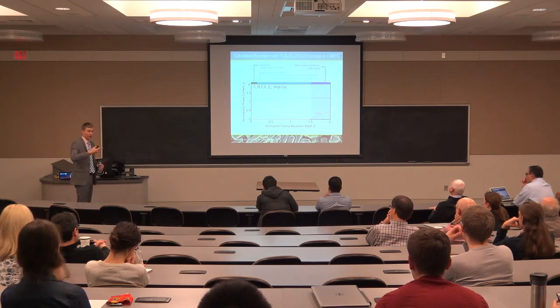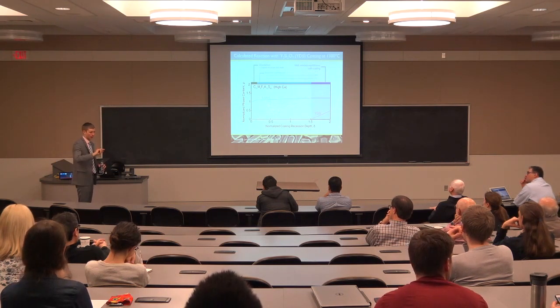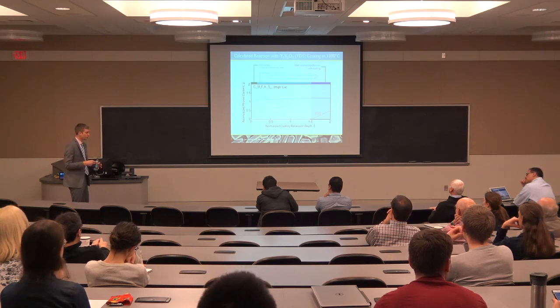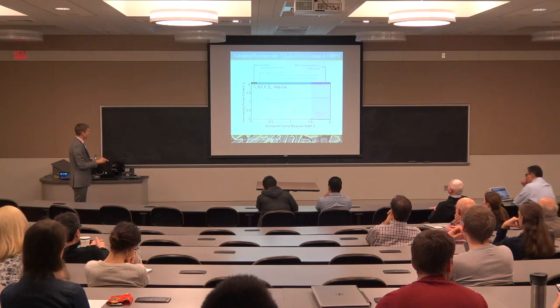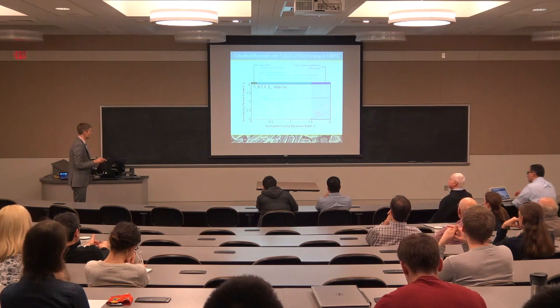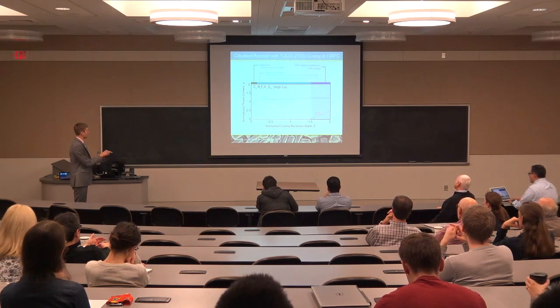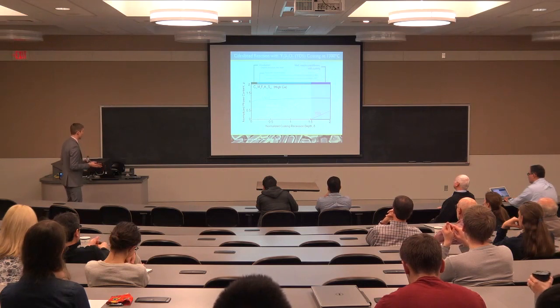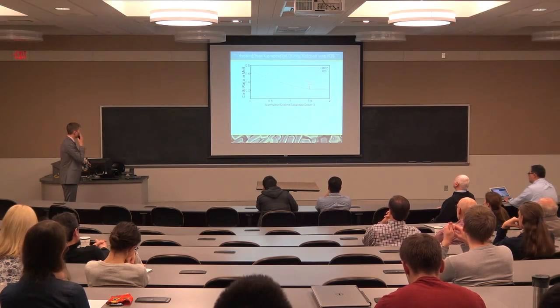It's basically an exchange of silicate and calcium from the coating material to form the apatite, but that doesn't consume the liquid at all. But then we eventually get to a point where this yttrium disilicate, which is the coating material, shows up as an equilibrium phase. We can basically draw a line here and say when we get to that point in the process, the reaction will probably stop and the coating recession stop.